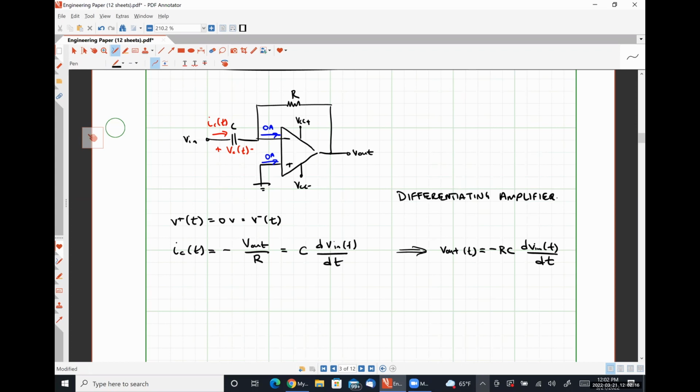Another reason that you see these capacitor-based circuits as well is that they are much easier to create using integrated circuit processes. Because if you're making an integrated circuit amplifier, forming a capacitor is very simple because you literally just put a layer of metal on top of another layer of metal and just make sure leads are coming out to apply your voltage, right? You can literally make a parallel plate capacitor by physically putting metal over another piece of metal. Making a coil in an integrated circuit is damn near impossible because all of your structures have to be planar.